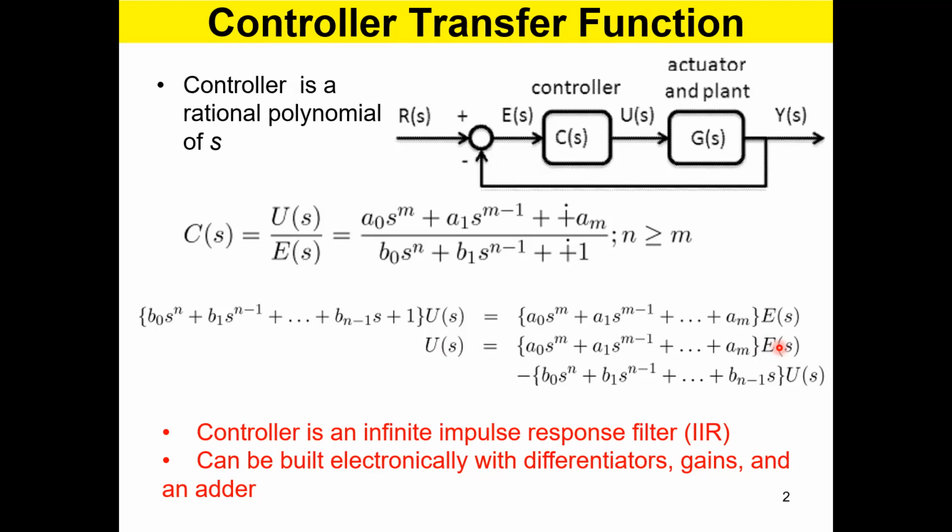So if you look at the time signal here, this is the error basically. You multiply the error with a gain. So in real electronics, you need to do this. Is there a way electronically to implement this multiplication? And then what you have next is the S term, S times E(S) with a gain.